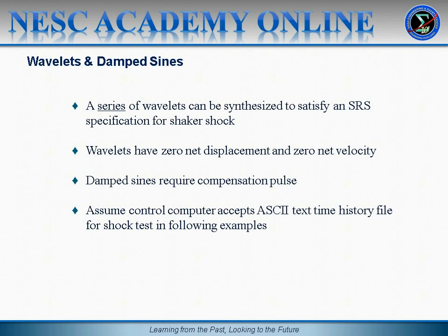Now the vibration control computer itself should have its own algorithm for generating a series of wavelets for an SRS specification, but we're going to come up with a MATLAB script in this unit which should be able to outperform the vibration control computer in terms of synthesizing a waveform which also minimizes the displacement and minimizes the acceleration. And these are two key limit parameters in terms of shaker shock testing.